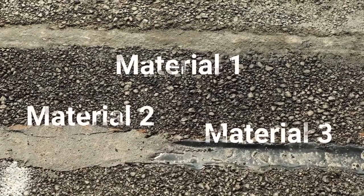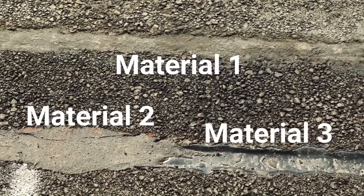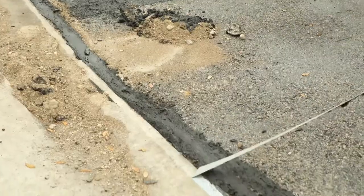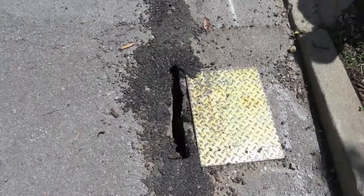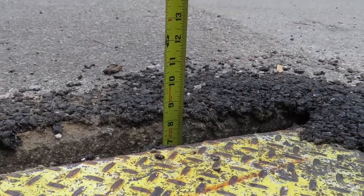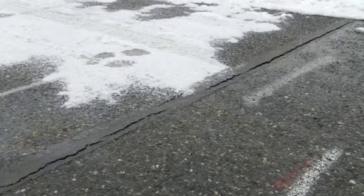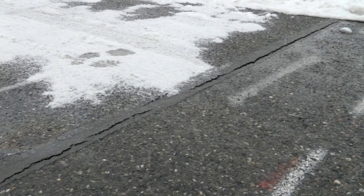Choosing the reinstatement material is the most critical consideration with microtrenching. Restoration, by definition, is the process of returning something to as near original condition as possible. Poor restoration causes issues like uneven settling, causing safety hazards to humans and animals, potholes in the restored surfaces, improper bonding allowing water penetration causing undesired soil movement or frost heave.